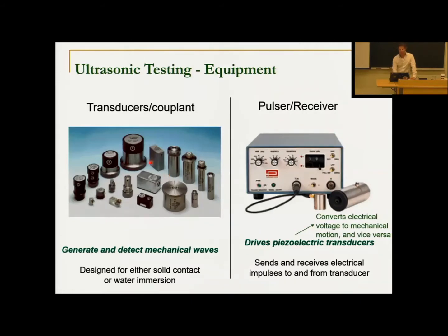In some cases, we can use water as a good couplant. For instance, put the inspected material into a tank of water, and with a specially designed, water resistant transducer, the water acts as the couplant. But this is very important: we have to have very, very good contact and coupling in order to get the energy through, and that can be an issue on a rough surface.